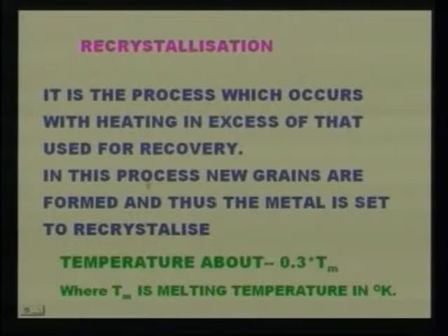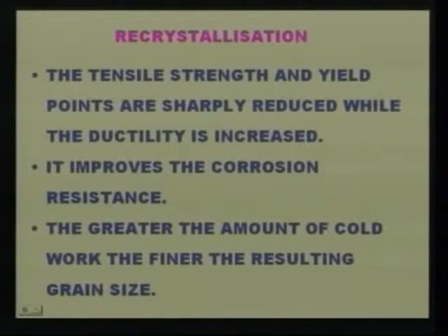Here the recrystallization temperature is about 0.3 times Tm for pure metal, whereas it is 0.5 times Tm for an alloy, where Tm is the melting point in Kelvin. Now, let us see some important points on recrystallization.